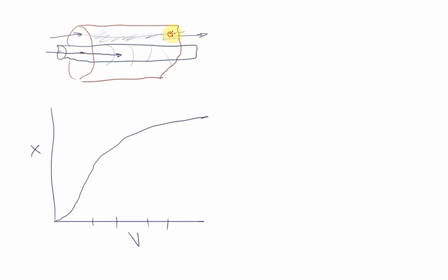So if it's approximately constant there, still it might be the case that the overall temperature difference will not generally be the same as the temperature difference up to any specific point, right? So the fact that the reaction mixture's temperature is changing along the tube also affects the degree to which the temperature will rise, and hence it also affects the degree to which the conversion will change.